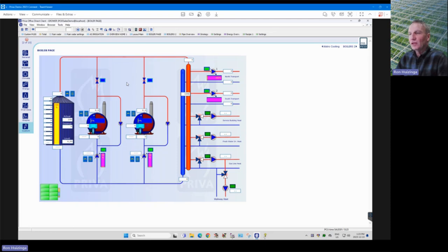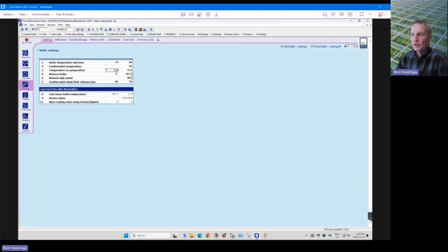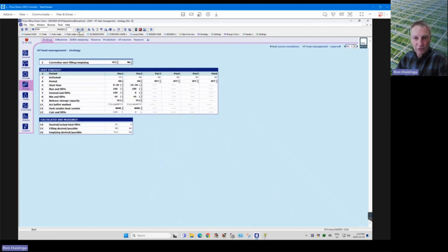Okay, good. So when that valve closes, that boiler will cool down. Sometimes it takes 6 hours or so to cool down from 90 to 70. It depends on how well insulated that boiler is, and as long as the valve here is not leaking. Once it gets down to 70, it'll go up to 73 or 74 and shut off. Then it might take a couple of hours to cool down to 69, turn back on again, and go back and forth. It'll do that on and off until the morning, until it's needed to fill the buffer tank to our minimum percentage, or the CO2 starts in the morning again and we start the boiler up.